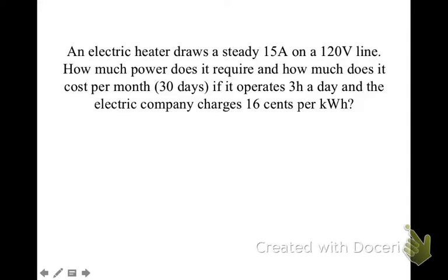So why don't you try one? Let's say I've got an electric heater that draws 15 amps on a 120 volt line, and that's a standard electric space heater. Tell me, how much does it cost to run it for 30 days at 3 hours a day? I turn it on every day for 3 hours, and I do that for a 30-day month. How much is my electric company going to charge me for that?